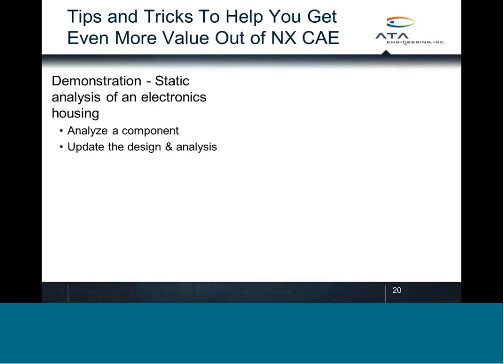That concludes the demonstrations we had planned for this webinar, so I just want to recap the tips and tricks we showed you today. The first thing we showed was static analysis of an electronics housing, and we saw this from start to finish. We started with a CAD model, created an idealized part, analyzed it, and saw that the stresses were too high. Then we went back to the idealized part, leveraged the synchronous modeling commands to update the design, did some trade studies and what-if analysis, and finally honed in on a design that was satisfactory from the designer's perspective and the analyst's perspective.